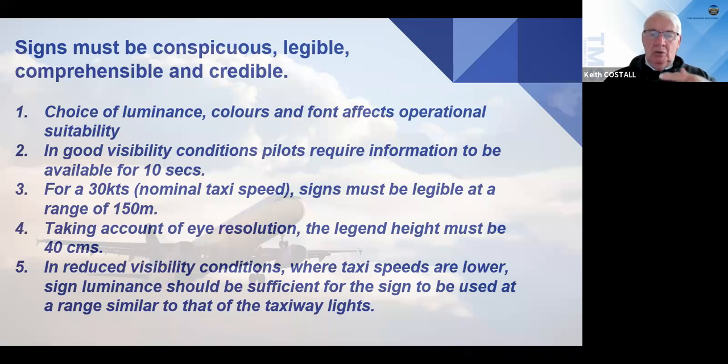The nominal speed for a taxiing aircraft was decided to be 30 knots. So that's two factors: 10 seconds to absorb the information, and 30 knots speed, because we know if you drive a car on a highway and you go fast, then you have less time to make decisions. That's where the speed element came in.